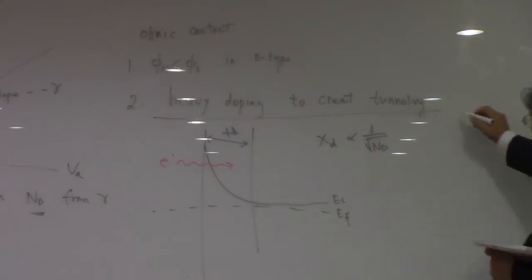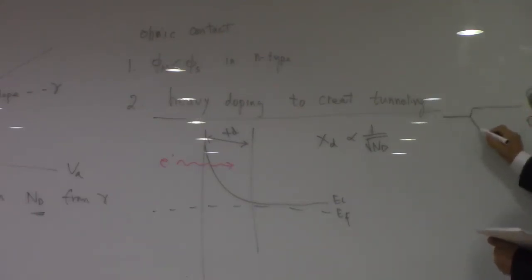like in a CMOS structure, we usually have field oxide to separate the transistors, and then if you use the P substrate, then you're going to have an N well, and then P plus junctions like this.